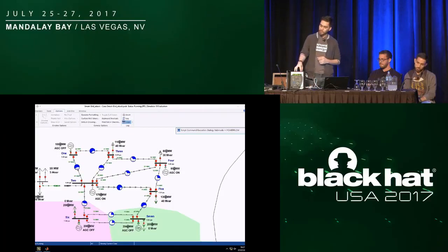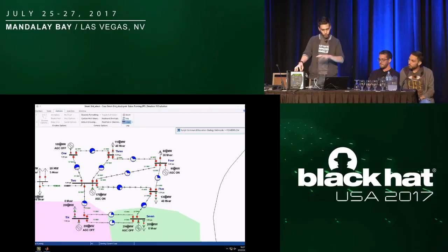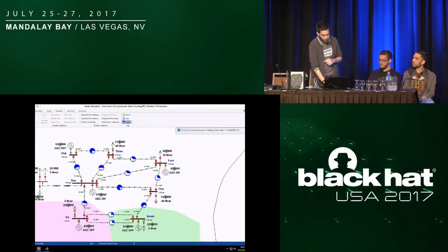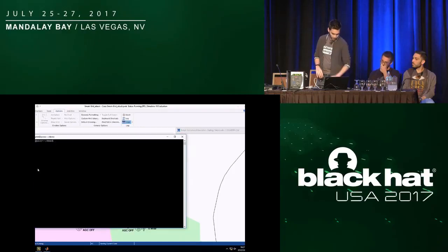And we have here a 750 relay device that's connected to the simulation model through a National Instruments data acquisition device. Essentially, the hardware here controls the virtual circuit breaker on bus number 8, the 10.7 megawatt load. Now, I want to begin by just pinging the device.